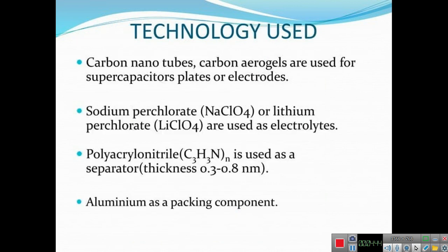Technology used: carbon nanotubes and carbon aerogels are used for supercapacitor plates or electrodes. Sodium perchlorate NaClO4 or lithium perchlorate LiClO4 are used as electrolytes. Polyacrylonitrile C3H3N is used as a separator, and aluminum as a packing component.